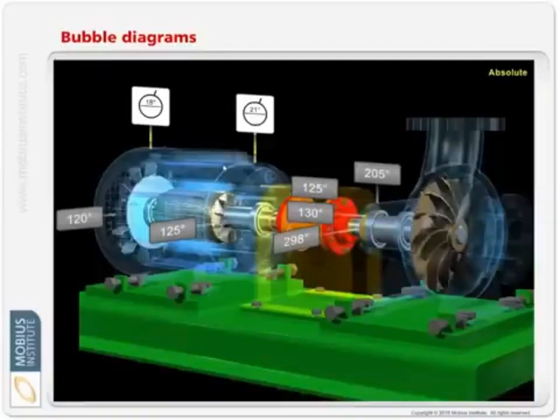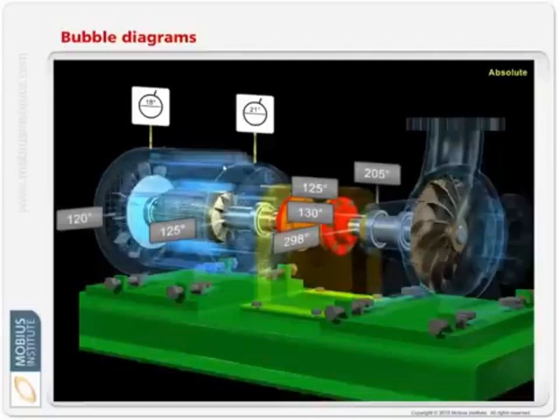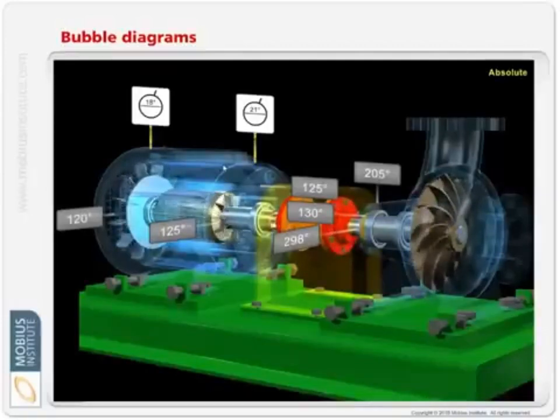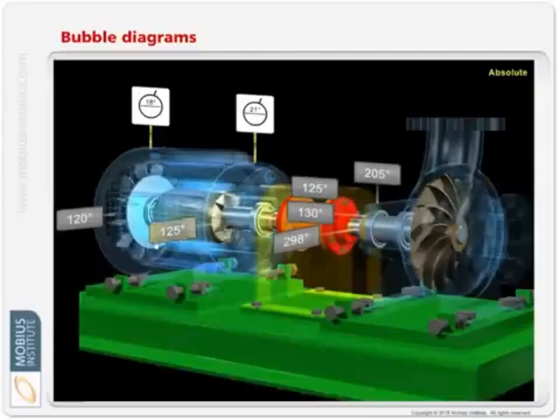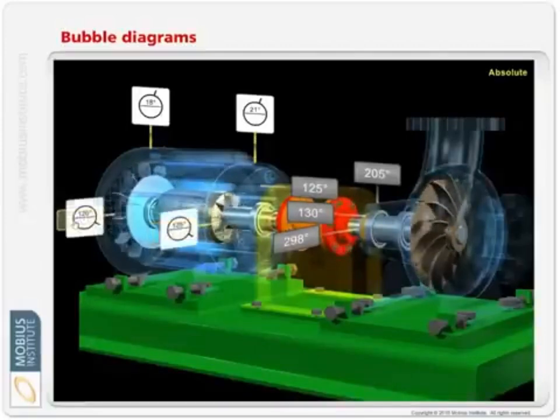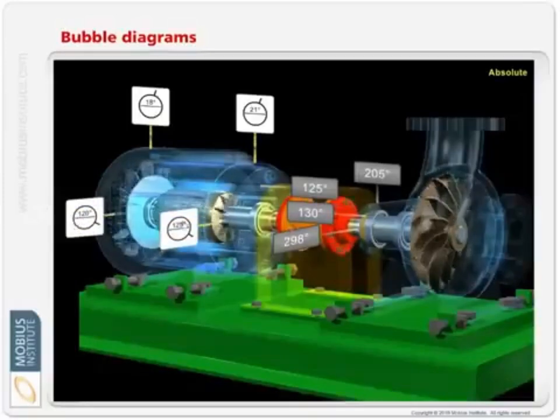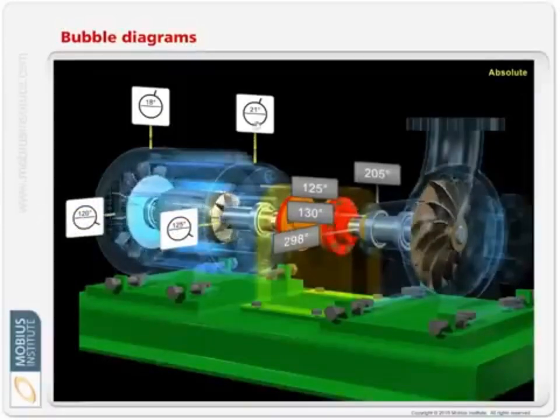In some fault conditions, we'll get one end of the machine moving down as the other end of the machine moves up. Or it may move down on one side of the coupling at the same time as it's moving up on the other when there's misalignment. So this all may seem a little complicated. It's just worth knowing that measurements like this exist. For example, here you can see that these ones are pointing down, or sort of down at that 45 degrees.